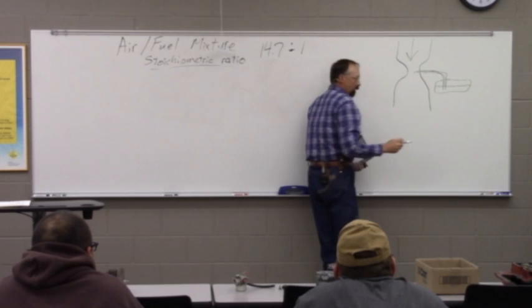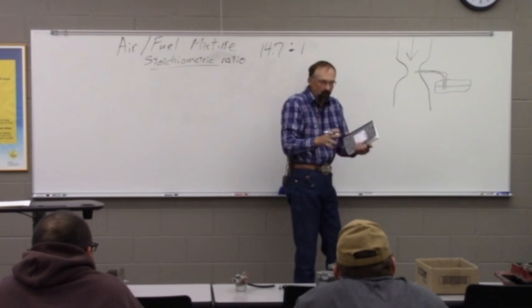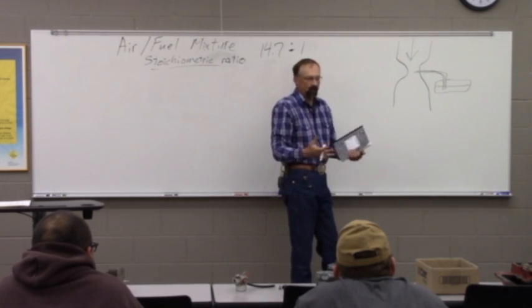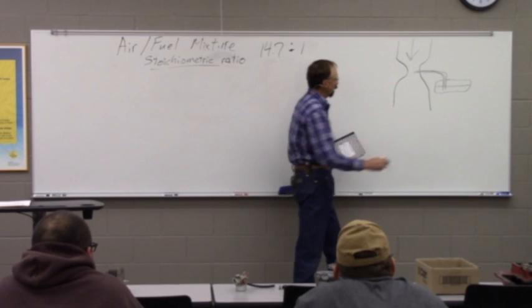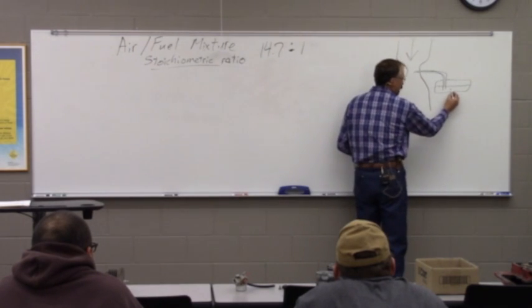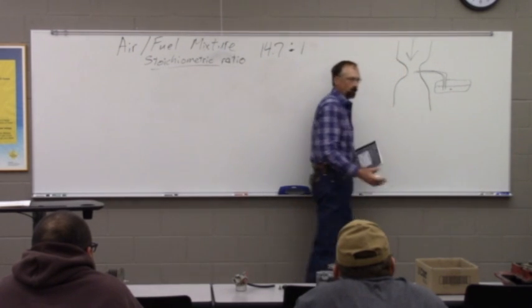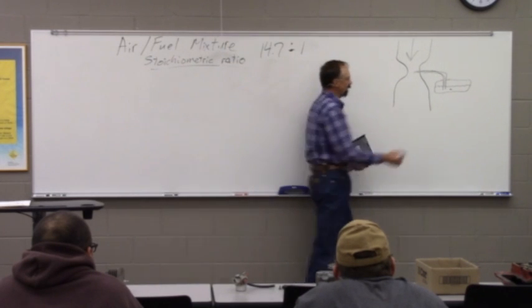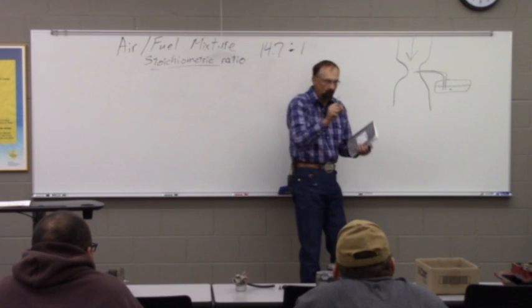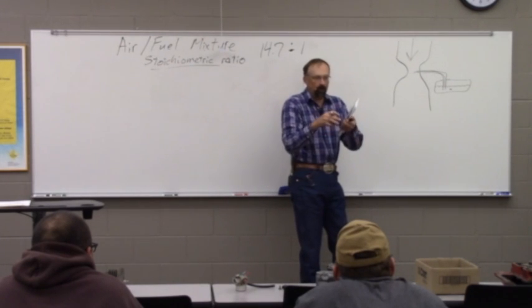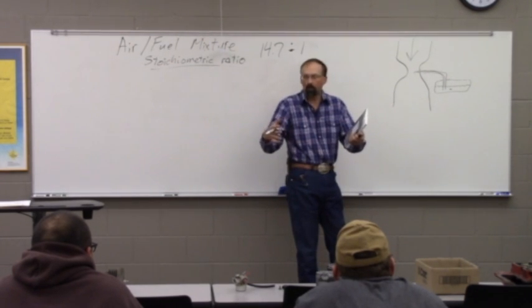As it comes out of the end of this tube, with all this air rushing through here, it makes this fine little mist, and gasoline vaporizes pretty readily on the surface. So down here in the middle of the liquid, that fuel doesn't want to vaporize so much, but the vapor that's on the surface here, and that's on the surface of all those little bitty droplets, it turns from liquid into vapor pretty readily.